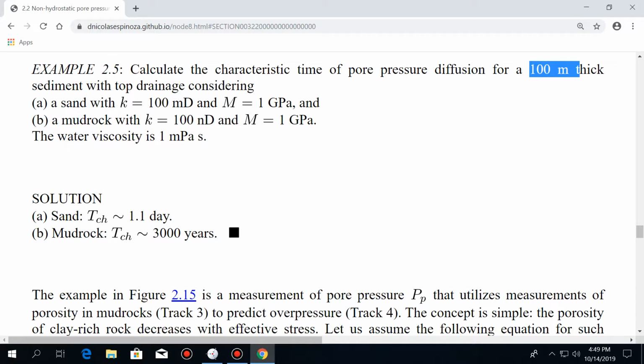So permeability here plays a very important role, because it varies by 6 orders of magnitude, so 1,000,000 times. And this is the difference you can also see over here. So if you have fast sedimentation rates, then it's very likely that you may have overpressure just because the water or any fluid in the sediments didn't have the time to escape.